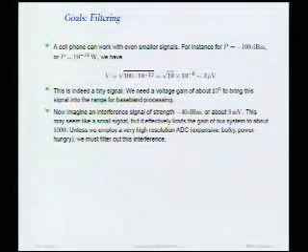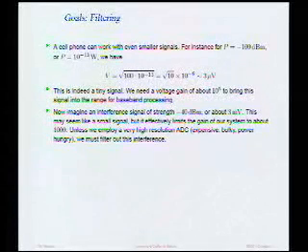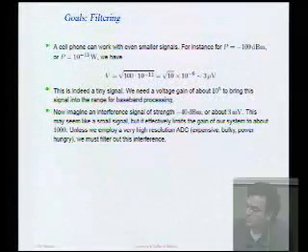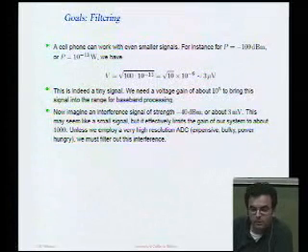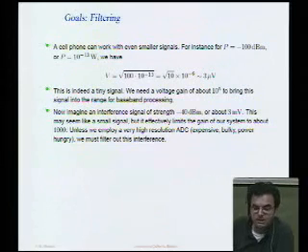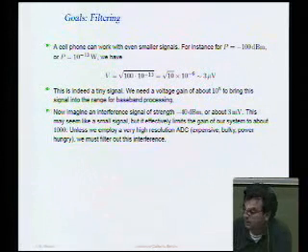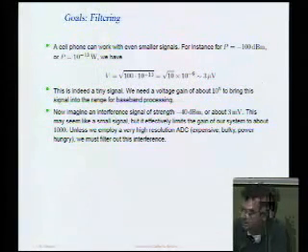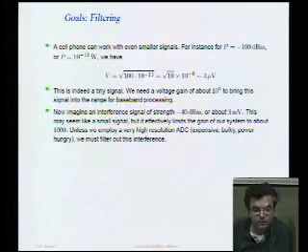But what about for a cellular phone? At the same time as you're receiving that wireless LAN data, you're also receiving a cellular telephone call, and the signal there is minus 100 dBm, and the cell phone has to work. Well, how small is that? That's 10 to the minus 13 watts. Using the same formula, if we translate that into a voltage, that's just 3 microvolts. Now that's a really small voltage.